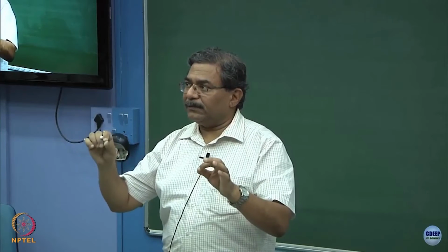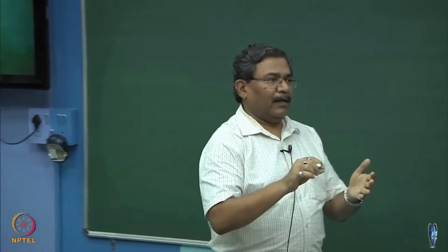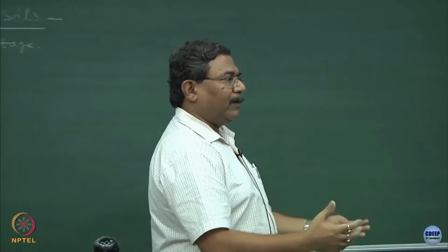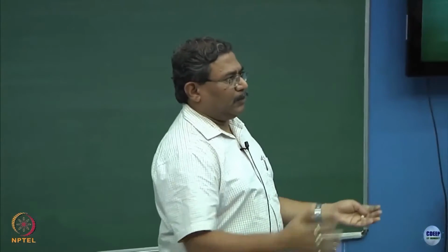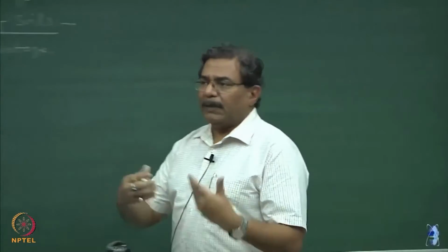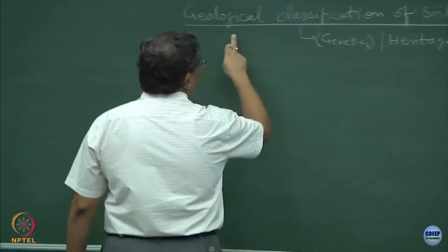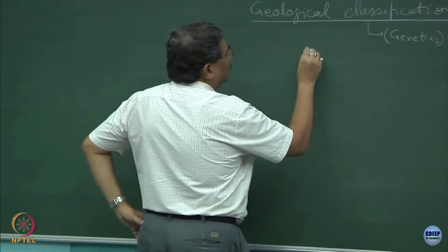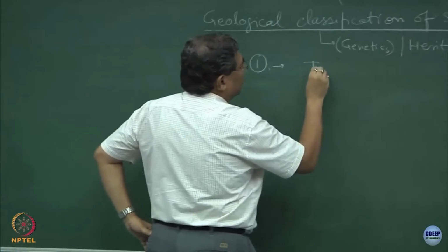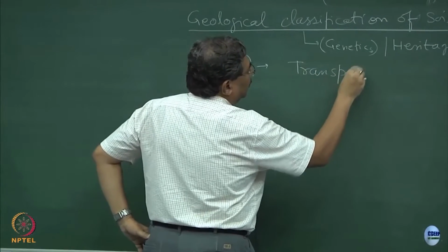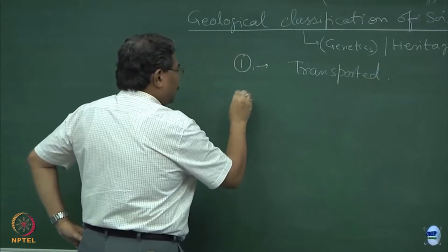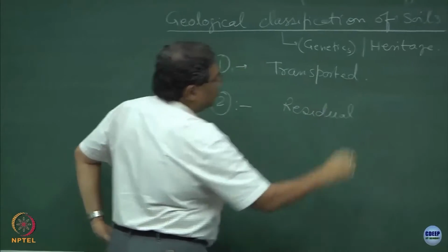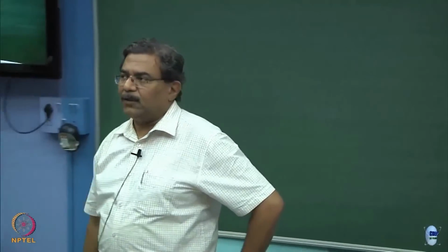Geo is earth, clear? Geotechnical. Techniques which are going to be used to understand the materials which are lying inside the earth or on the earth, geotechnical, clear? And engineering with those materials. So, when we talk about this, the first thing which comes to the mind is, these are 2 broad characteristics. The first one is transported, and I think you are all aware now what transported soils are, and the second one is the residual soils.